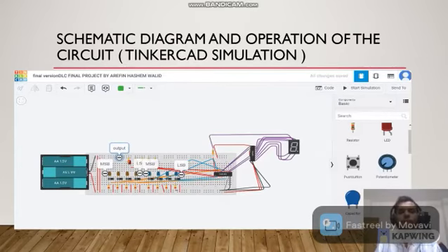In this device, as you can see, the switches will give the signal high and low as 1 and 0. The device will take the signal from LSB to MSB. We have a total of 8 inputs. The first 4 inputs we have shown using orange LED lights, and for the second 4 inputs we have used blue LED lights, and for the 5 outputs we have used red LED lights.